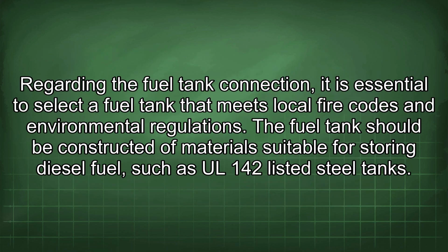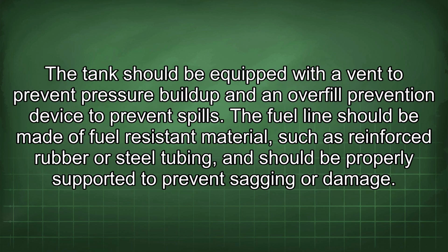Regarding the fuel tank connection, it is essential to select a fuel tank that meets local fire codes and environmental regulations. The fuel tank should be constructed of materials suitable for storing diesel fuel, such as UL 142 listed steel tanks. The tank should be equipped with a vent to prevent pressure buildup and an overfill prevention device to prevent spills. The fuel line should be made of fuel-resistant material, such as reinforced rubber or steel tubing, and should be properly supported to prevent sagging or damage.